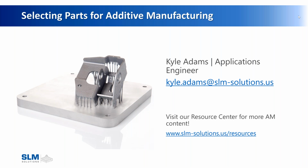So as the part you see here on the screen, inside the machine, that would be completely covered. That 280 millimeter square would be completely filled with powder, and that part would be buried. We'd need all that material there, and then all that material just gets brushed away. It's still soft, it's still powder, so it gets brushed away and you're left with what you see here on the screen.